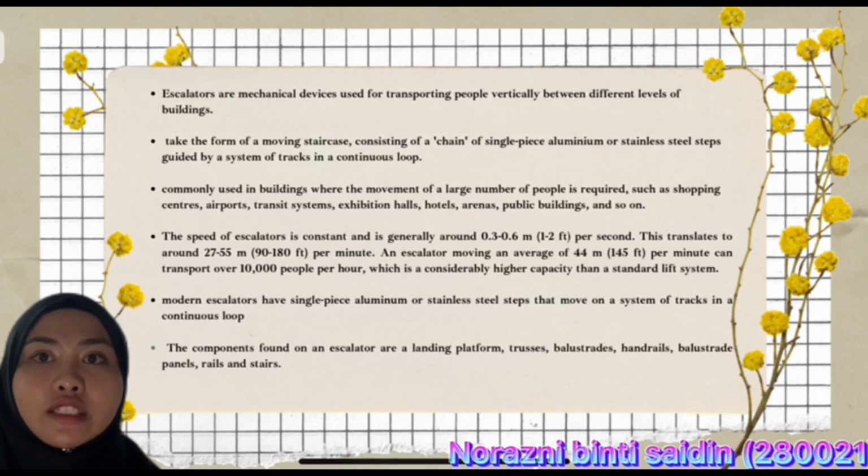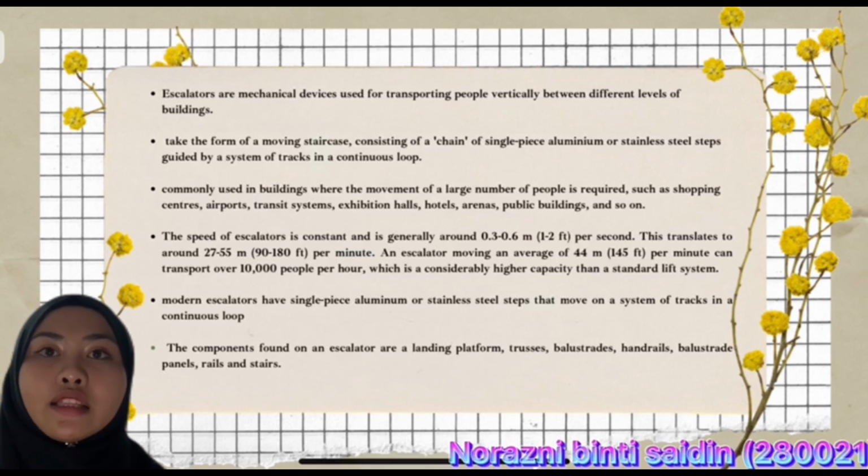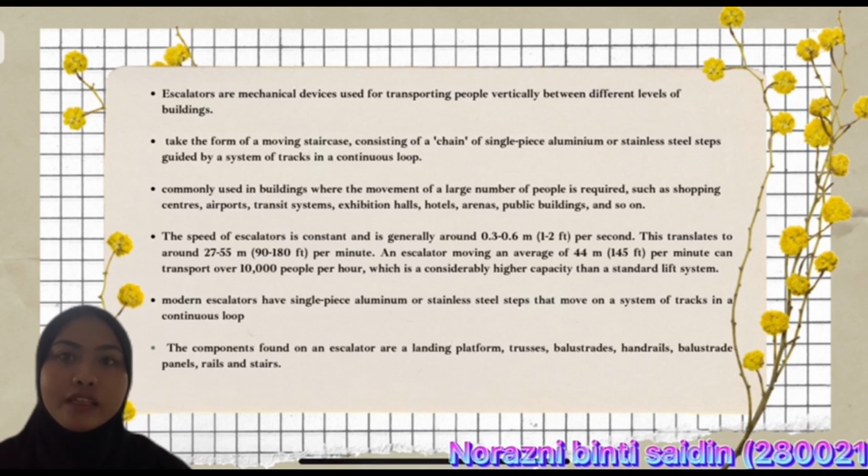The speed of an escalator is constant and is generally around 0.3 to 0.6 meters, or 1 to 2 feet, per second. This translates to around 27 to 55 meters, or 90 to 180 feet, per minute. An escalator moving an average of 44 meters, 145 feet per minute can transport over 10,000 people per hour, which is considerably higher capacity than a standard lift system.